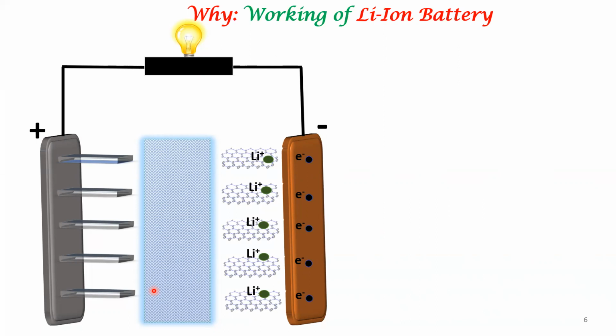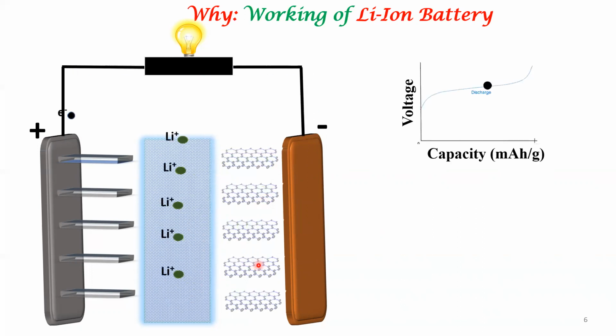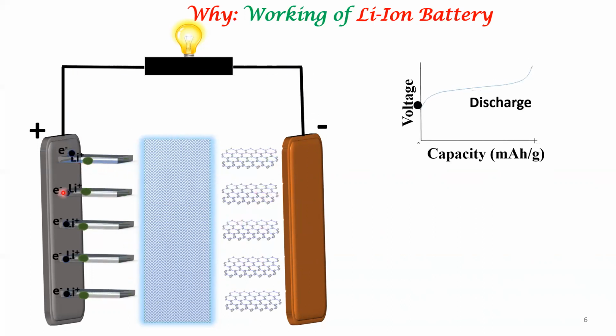Here we give a schematic illustration of the working principles behind a lithium-ion battery. So in the charged state, lithium ions are intercalated into graphite, the anode, for example. As the battery gets discharged, the lithium ions are translocated across the electrolyte and intercalate or bind to the cathode structures, materials of the cathode structures. These cathode structures are typically transition metal oxide structures.